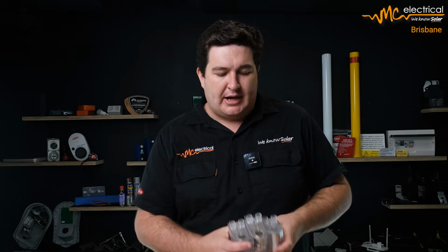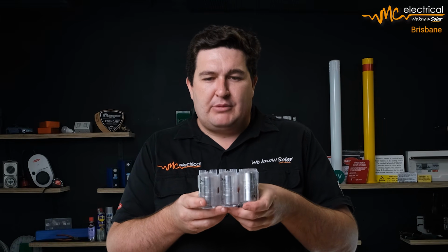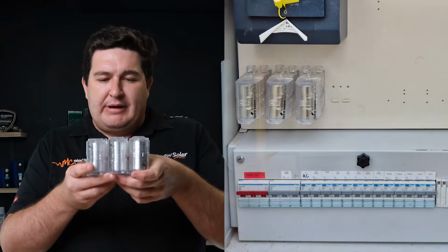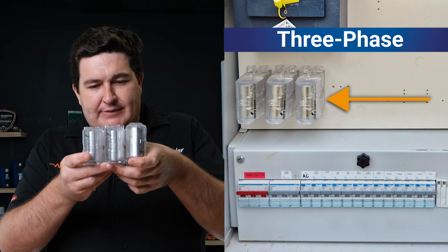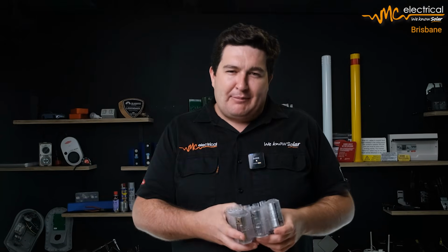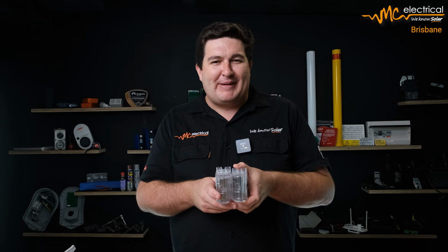Now, another way you can tell if you've got single phase or 3 phase is you can have a look at isolation links. So most new switchboards and meter boxes will have these isolation links. And it's a way for Energex or a fireman to turn off the power to your house in an emergency without having to get up on the pole and pull the pole fuse. Now, on 3 phase, you'll have 3, again, 1 for each active cable. On single phase, you'll only have 1. So again, this is a very easy way to check when you open up your meter box how many phases you have. Some homes, you might have 2. Now we call that 2 phase, but we'll talk about that in another video.